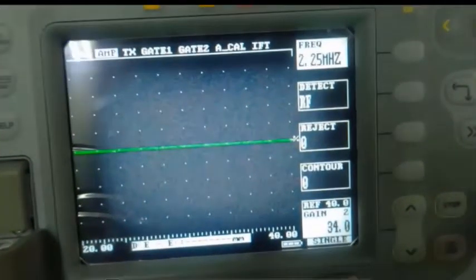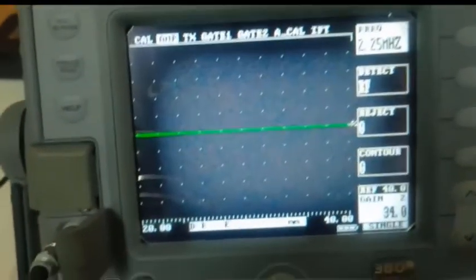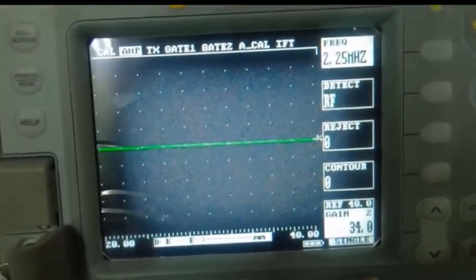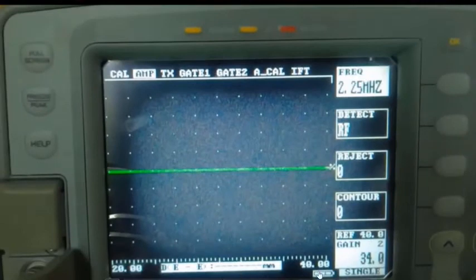So the frequency is set, as you could see, depending on the transducer which is chosen. So a transducer will have a particular frequency. So that frequency is set over here. And after that, you will also have to select whether it is a single or dual element probe. So this is where you can do that using this particular press button. So we have selected a single element probe. So this is going to be set as single, as you could see right now.